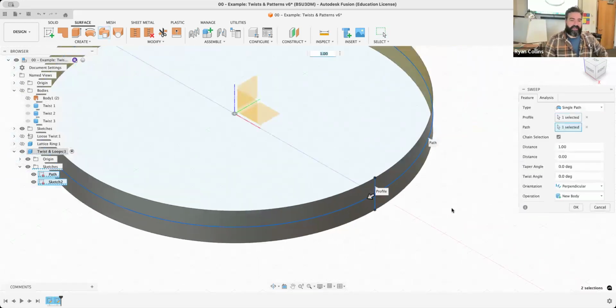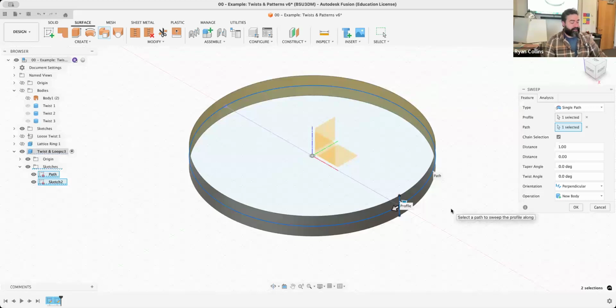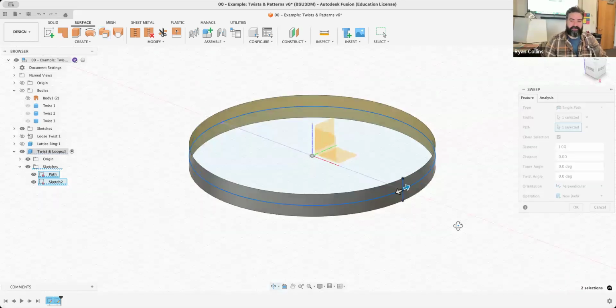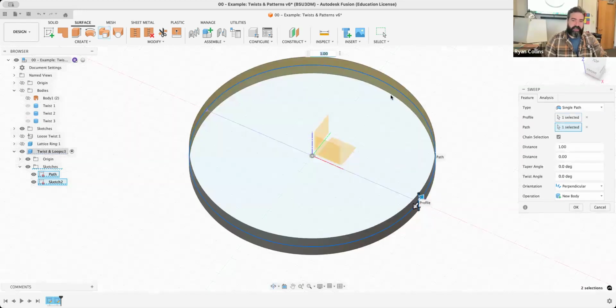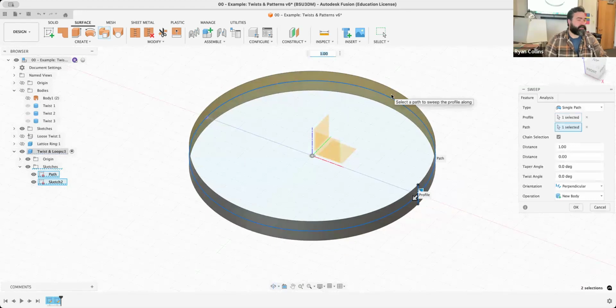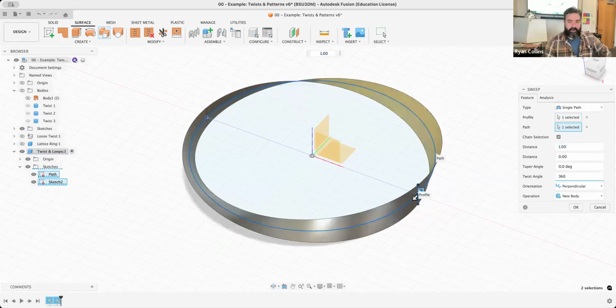My path is exactly the same there. You can see it's expressed the exact same way as an unthickened form tool, so form surface. It's colored on the outside, or whatever the appearance is, and then this gold color on the inside. That's it. But with this, I'm going to apply the twist like we were playing with before. Remember, it has to be in increments of 360. All right, cool. Let's bump it up a lot.